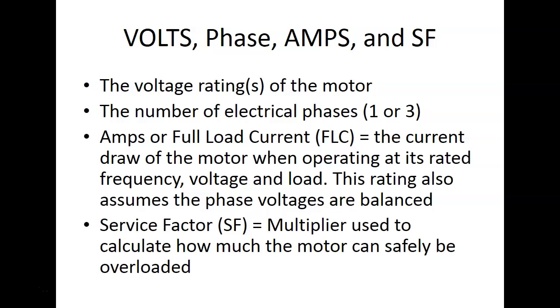Everybody okay? Of course, phase, what's that? Single phase, right? Or what? 3 phase. We only got 2, right? The code, what does the code tell you? To start it, right? It gives you the range of currents that the motor says it will take. If you can't find that information, then the rule of thumb is what? 6 to 8. But like I said, these days, it's hard not to find this information.